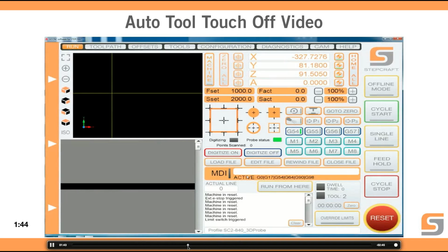Now, say you break a bit, or you have one tool, like tool number 3, that for some reason you want to change out. Maybe the bit's getting dull and you want to put a new one in. So you would replace the bit, put the tool holder back in the rack, and hit M4, except this time it's going to ask you how many tools you want to replace. You're just going to put in number 1. When it sees that you only want to change one tool, another window will pop up and it'll say, okay, which tool do you want to change?